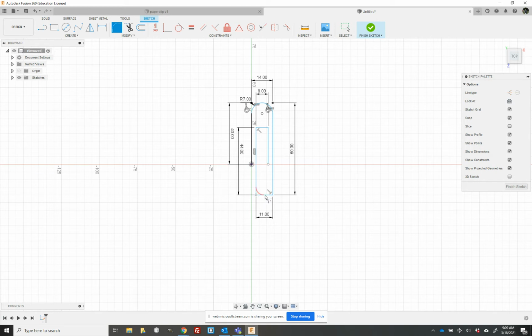Why am I doing these separately and not all at once, like I've done in previous projects? Different dimensions. These next two corners are a distance of 11 millimeters. And we've seen, like with our plug example, that if we want to round it off in a nice symmetrical arc, it is the distance between the two points divided by 2. All right, so this one's going to be 11 divided by 2. 11 divided by 2 happens to be 5.5.